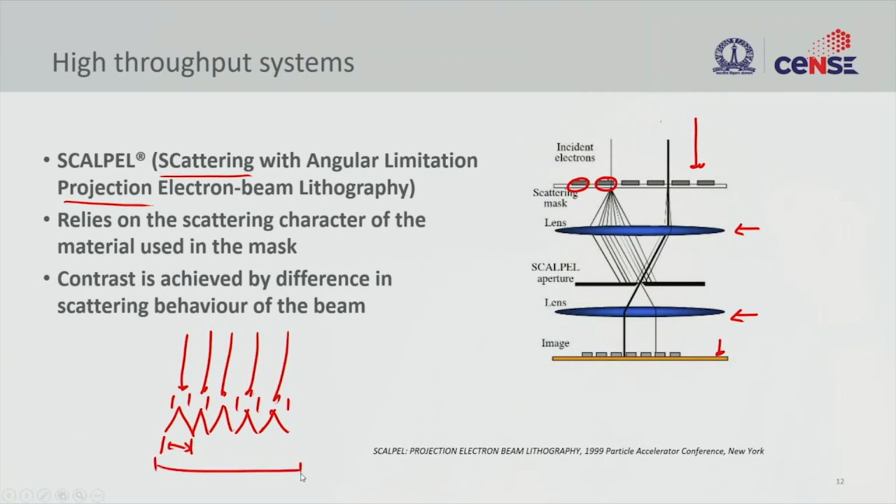Initially with a single beam, this was your write field delta x, let's say, but now n number of beams will increase my write field by the same quantity. So there are thousands of beams that one can use in order to do that, and that is called multi-beam writing, which is explored very seriously as an alternate writing process for next generation CMOS.